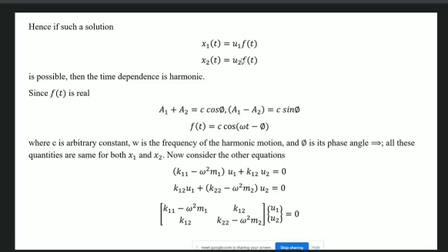When a particular mode is maintained, then the system is bound to vibrate in a particular frequency, which we call the natural frequency. The lowest natural frequency is called the fundamental natural frequency, and the corresponding time period, that means 2 pi by, if the lowest natural frequency is omega 1, then 2 pi by omega 1 is equal to the highest natural period. And this mode, normally the lower modes, they participate more in this kind of vibration, because